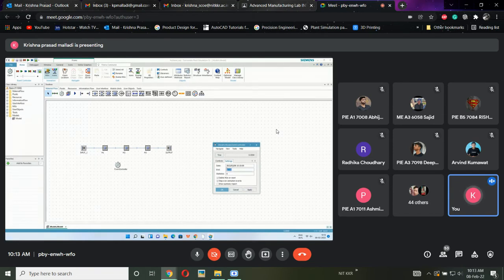Now I want to run the simulation for 2 hours. Then for that I need to press 2 and at the same time 2 colons. Apply. See, 2 hours, 00 minutes and 00 seconds. Same, if I want to run the simulation for 10 hours, 10, 2 colons, apply, 10 hours.